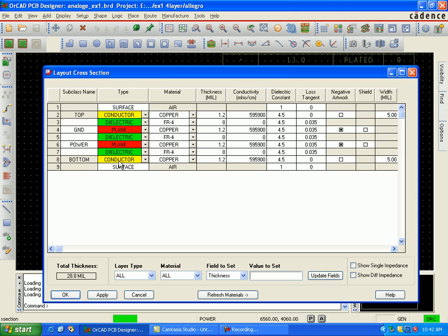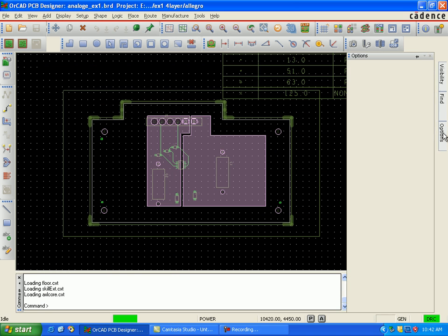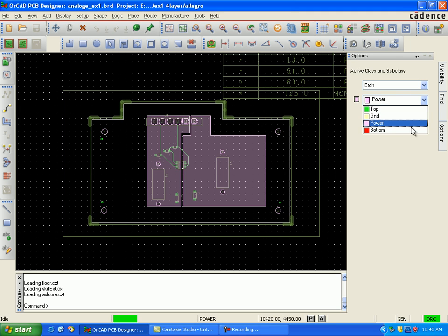See the layers. This is a 4 layer. Because the cost of a 6 layer was like $500, I made the PCB a 4 layer. I decreased the layers by not giving the V positive and V negative on 2 layers. I made it on 1 layer.